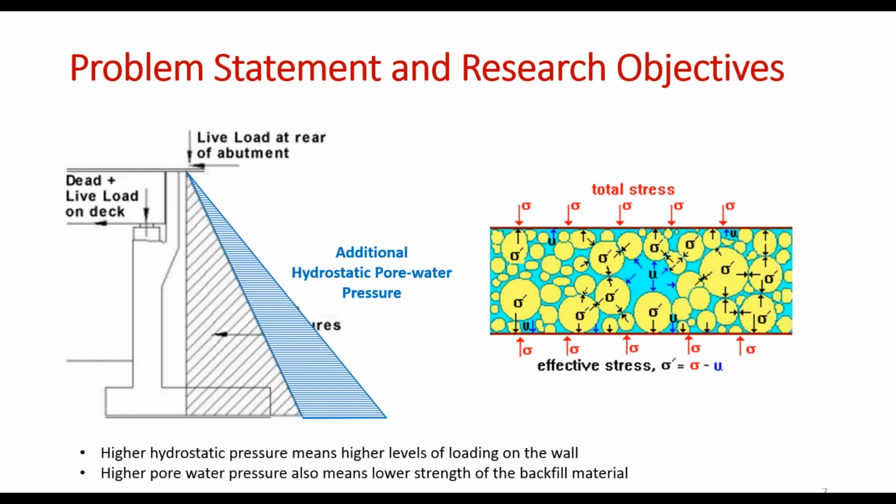On the other hand, larger water pressure will reduce the effective stress inside the soil, reduce its strength, and change its deformation properties. So it's a very critical matter. We need to deal with this water.